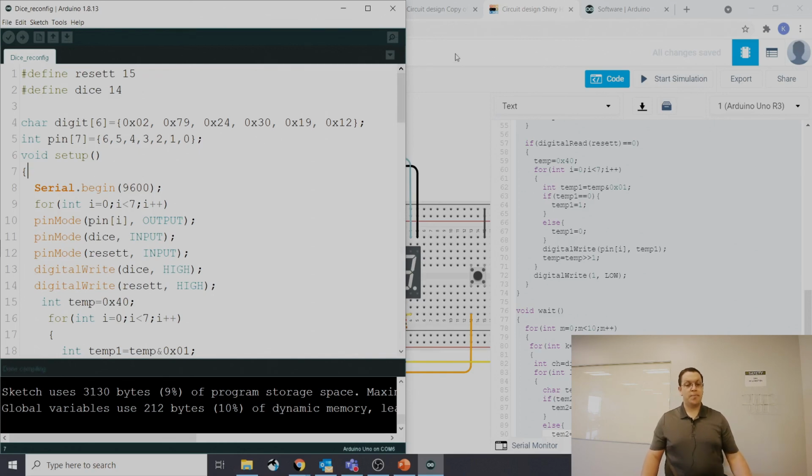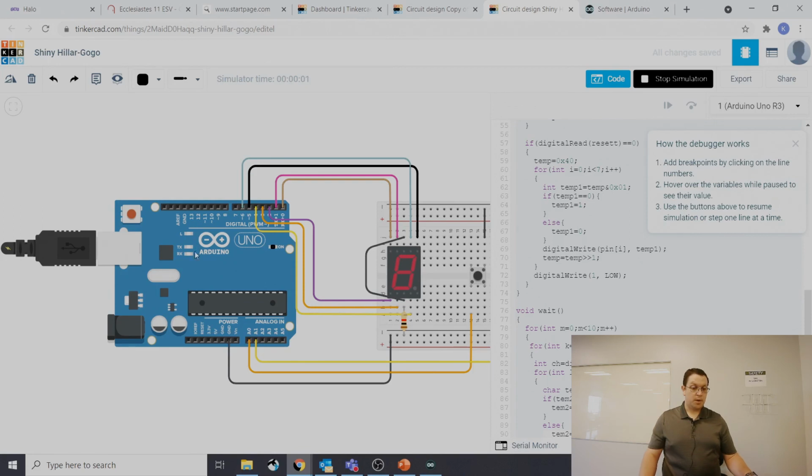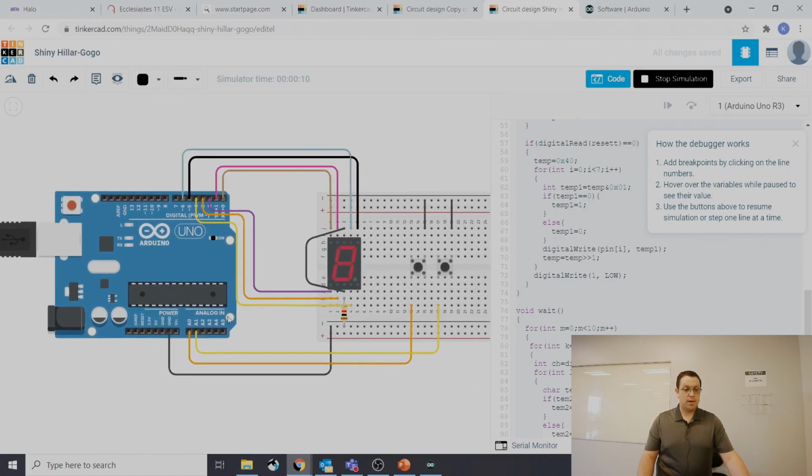If you do not get this light showing up on your board, there's a green LED here that will light up as on, and then there should be a blinking LED here that's loading content when you actually start it up. If that's not happening, and you have everything dark, and you notice this spot on your Arduino Uno getting really warm, probably what has happened is you have inadvertently crossed power and ground somewhere, so you want to go back and really double check connections to make sure they are correct.